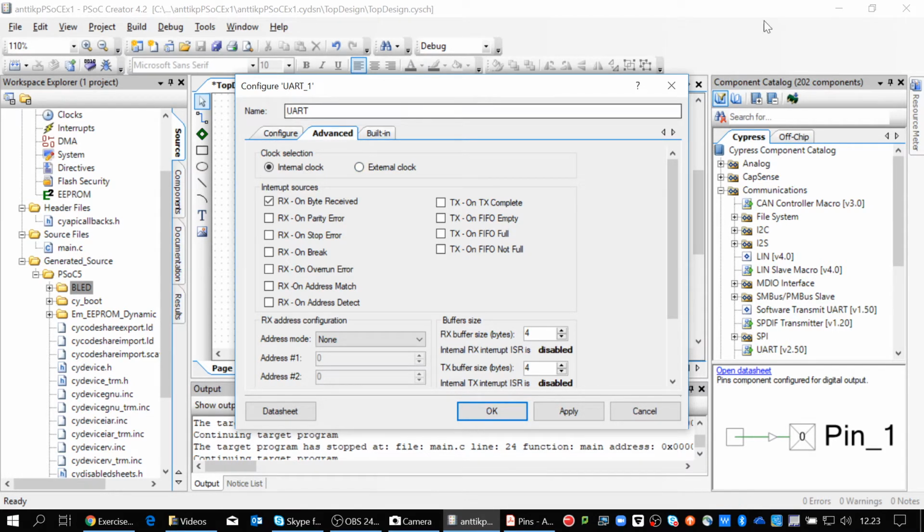In case you are running short of resources, you can employ the external clock, since then you can use some logic function, a frequency divider, to provide a clock rate for this module and not use the internal clock. The internal clock is generated automatically, but it also takes one of the clock sources from the common resources.